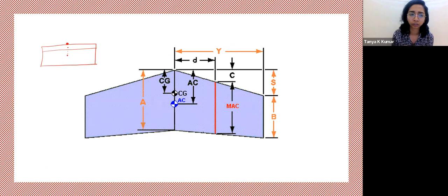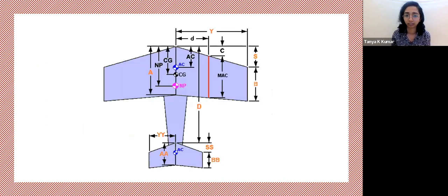Our professor also made us do a wing tail configuration. You can try that. So your CG should be ahead of the AC for a wing alone configuration for stable flight. Now, if it's a wing tail configuration, when it's just a wing, your aerodynamic center is where we base all our calculations.